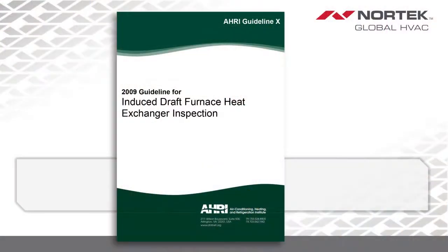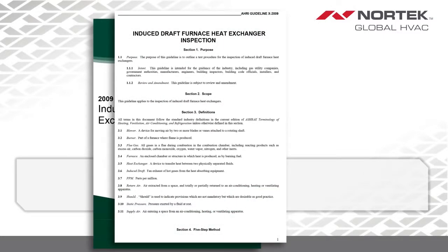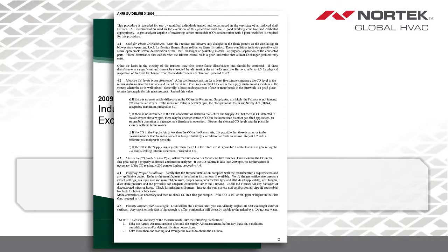If they were to call in and say, I believe I may have a problem with this particular gas furnace, this heat exchanger, here are the 2 methods that I used. First, I used my combustion analyzer, and here was my data. Here's exactly where I took my samples. I followed the AHRI guideline for an induced draft gas furnace heat exchanger inspection, the 5-step method, and here's what my data said. I followed that up with a smoke test, and here's what happened. Between those 2 test procedures, I believe I have a problem with the heat exchanger and that it most likely has a breach. I'd rather be safe than sorry.